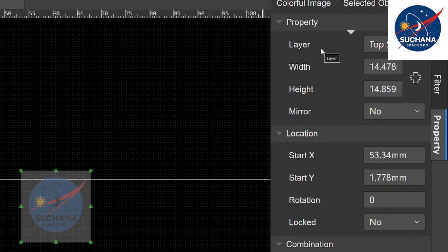Only if it is in the silk screen layer will it appear on the top of the PCB, because only the silk screen layer can show designators, symbols and all other text, symbols, images, everything for human readability purposes. They do not contain any kind of electrical conductivity properties. It is completely made with non-conductive inks, non-conductive resin, epoxy resin.